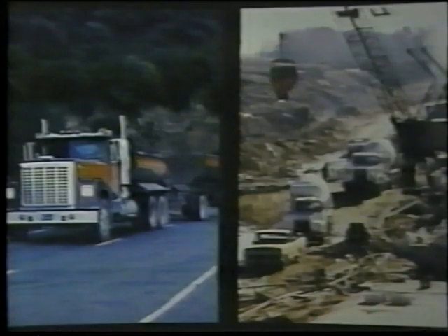On the other hand, rougher driving conditions may increase wear. If a transmission previously driven under moderate highway conditions is going to be rebuilt and installed in a truck operating under more severe conditions, then gears that are already showing signs of advanced stages of distress cannot be expected to wear at the same rate as in the past.